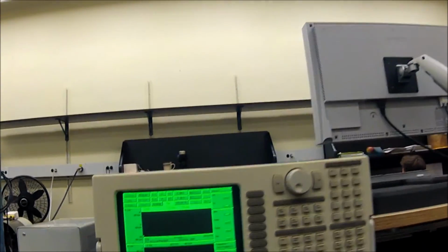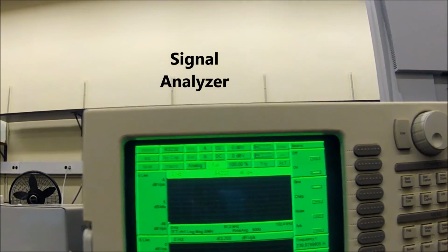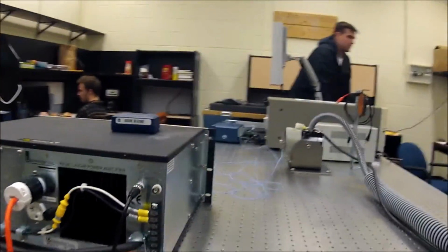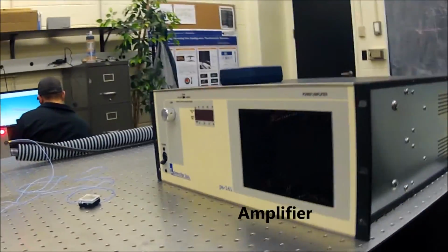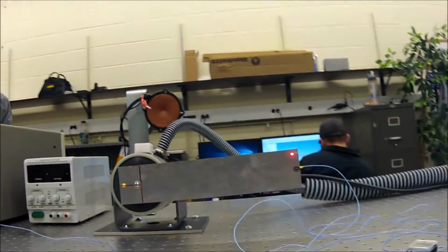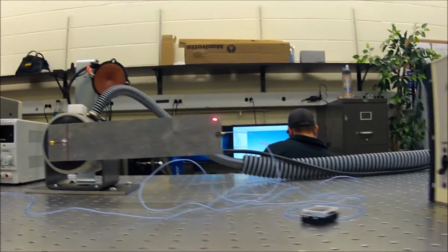The experimental setup contains two main parts. The first part involves generating a sine signal with the signal analyzer. The signal varies from 0 Hz to 350 Hz. This signal is transmitted to the amplifier and to the computer. The amplifier controls the shaker. The accelerometer monitors the displacement at the free end of the beam. This displacement is sent back to the analyzer to obtain the frequency response.